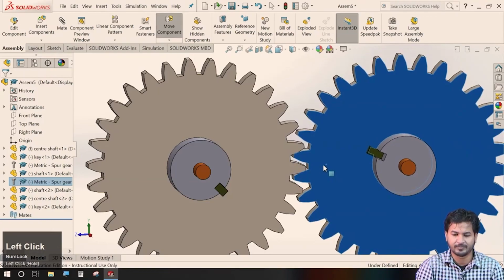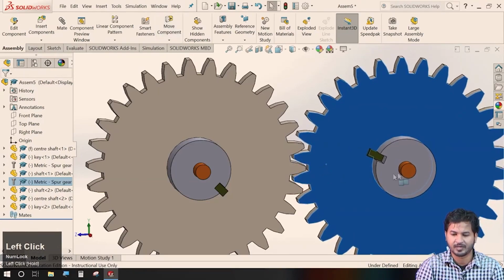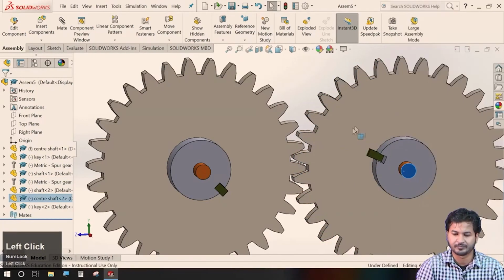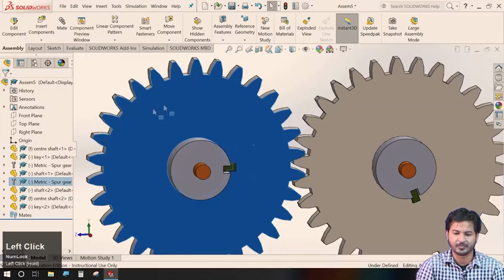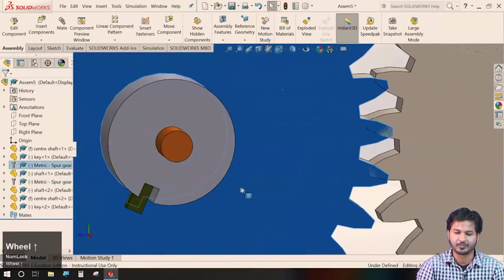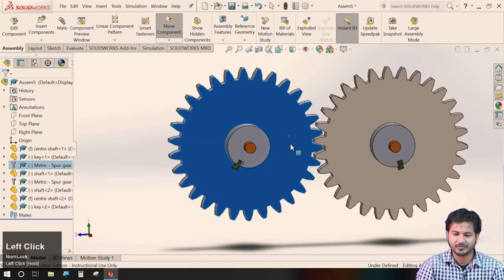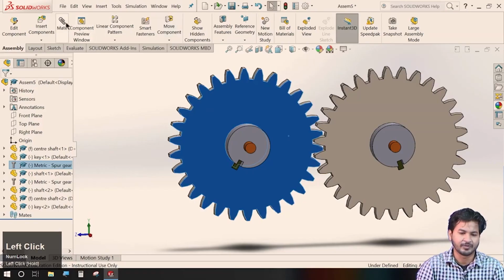Let's just place it well, and we will fix this shaft. So you can see this moving, and also this one. However, there is no relation as of now. So this relation is featured by this gear mate available in mechanical mates.